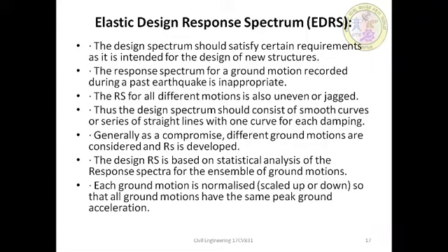The design response spectrum is based on the statistical analysis of the response spectra for particular ground motions. Each ground motion is normalized, scaled up or down, so that all the ground motions have the same peak ground acceleration. The response spectrum of each normalized ground motion is considered.